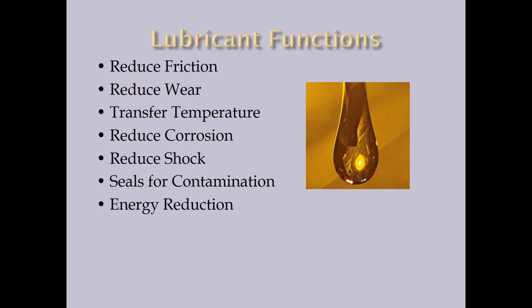There was a company in Ohio back in 2001 that actually measured the energy consumed on every piece of equipment in their plant for a period of 6 months. And at the end of 6 months, they changed out all the petroleum-based lubricants, they added synthetic lubricants, and they actually reduced their energy at their facility by 9.8%. So lubricants can reduce energy.